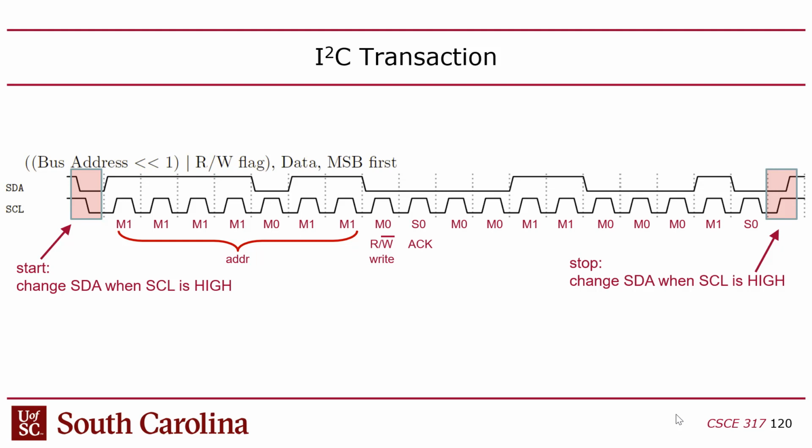And in this case, if it's 0, that means I'm writing, which means that first of all, the acknowledgement is the next one from the slave, and then I transfer over and I send 8 more bits on the master, and then the slave will acknowledge at the end of that. You guys with me? So there's 18 total bits that are sent.